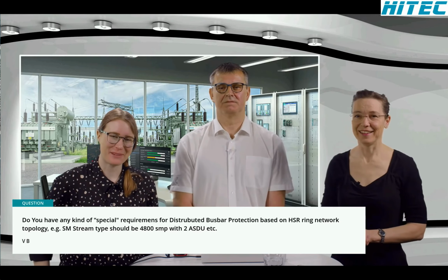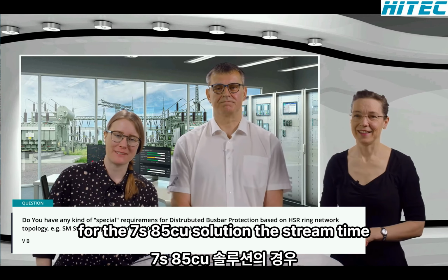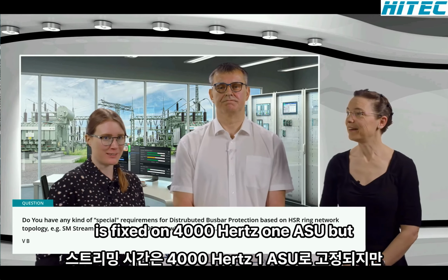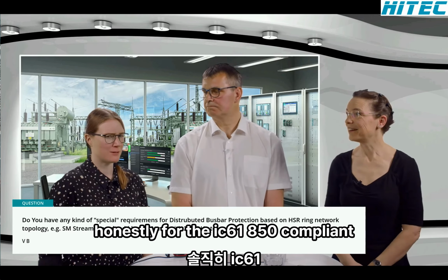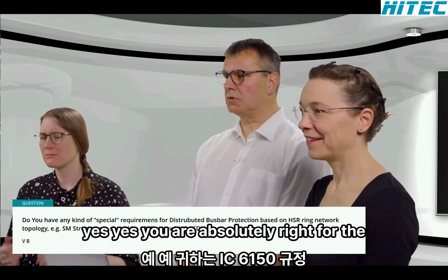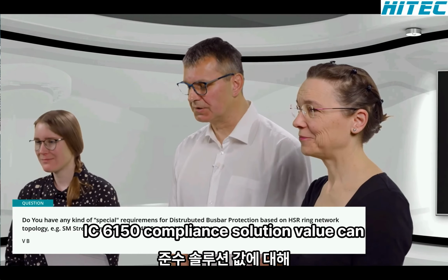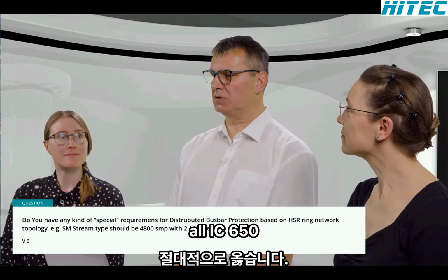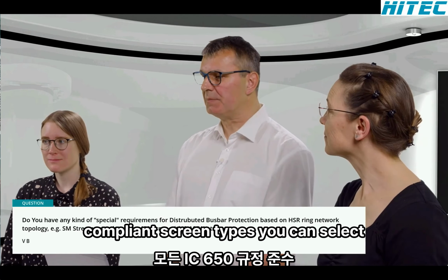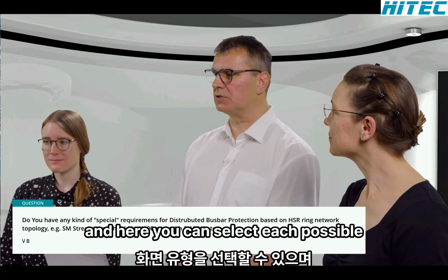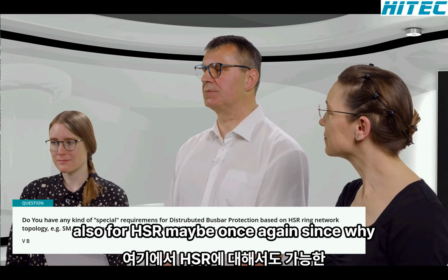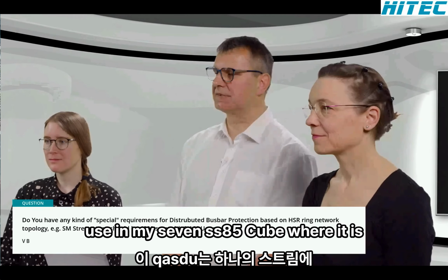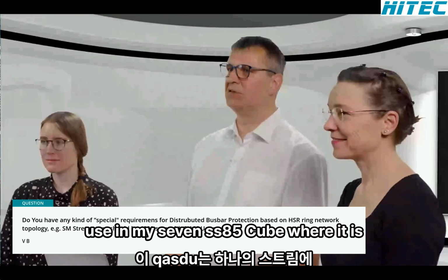I can say that for the 7SS85CU solution, the stream type is fixed on 4000 Hertz 1 ASDU. But honestly, for the IEC 61850 compliant solution, both is possible, I would say. Yes, you are absolutely right. For the IEC 61850 compliant solution, you can select all IEC 61850 compliant stream types, and here you can select each possible also for HSR.